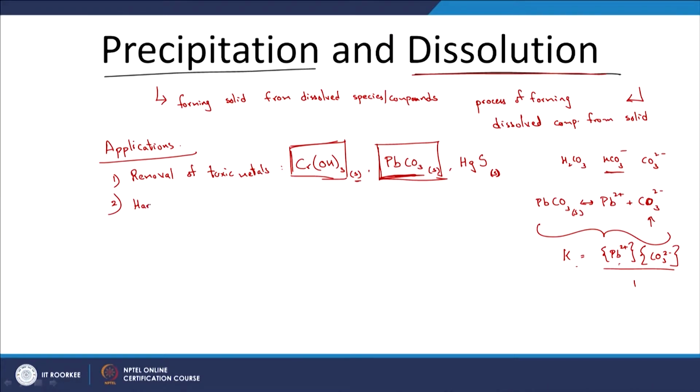There are different methods, but almost all of them, what is the principle here? It's precipitation, in the form of CaCO3 solid and Mg(OH)2 solid. So as you see, calcium carbonate can precipitate out. What's the requirement here? Obviously you need to keep the pH high. Why is that? Because if you don't keep the pH high enough, CO3 2 minus would exist as HCO3 minus. So CaCO3 depends on the relevant acid base process, and Mg(OH)2 again depends upon pH.